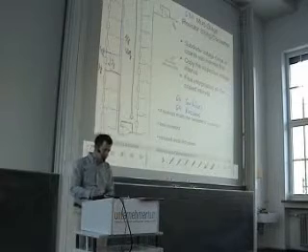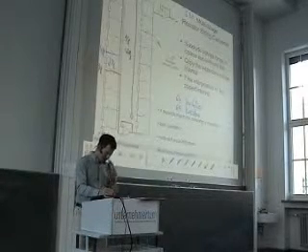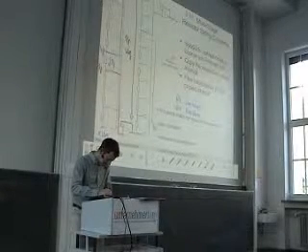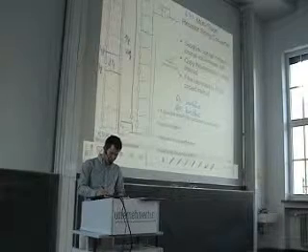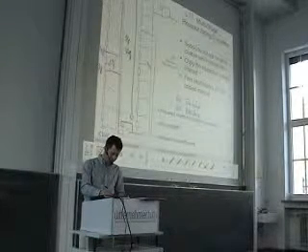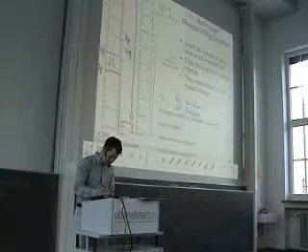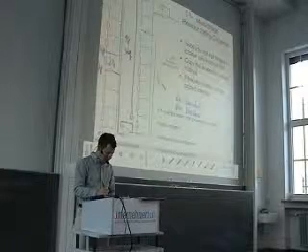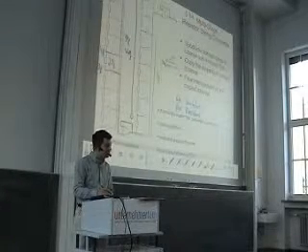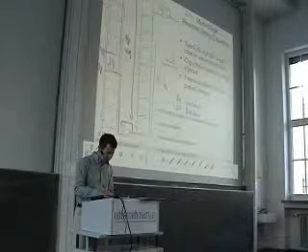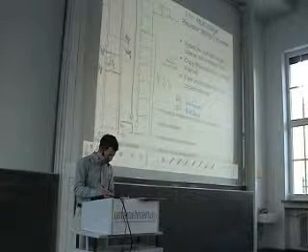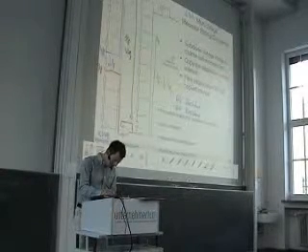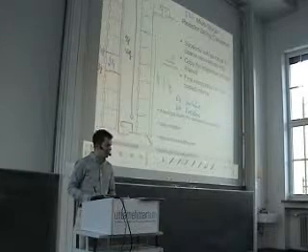Well, the voltage that we have from this node, excuse me, from this node to this node, this is 0, 1, 2, 3, 4, 5, 6/8 times the voltage we have over the complete string, and this was 1/8 times Vref. This is the voltage from here to here.